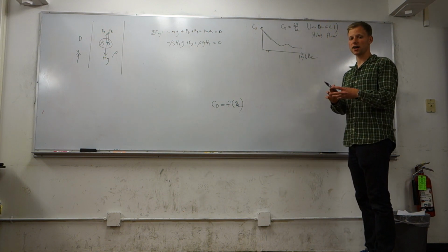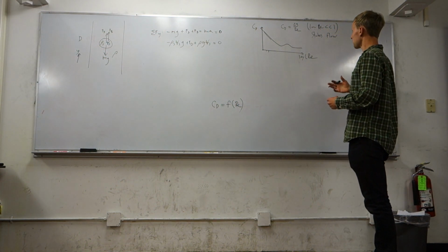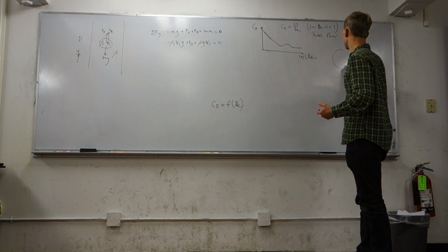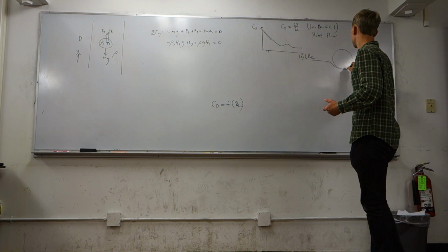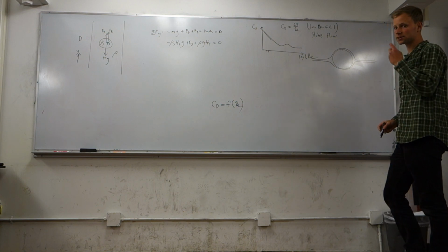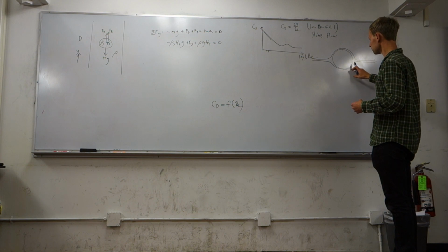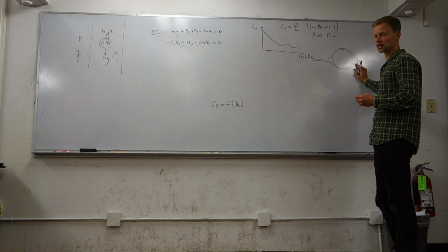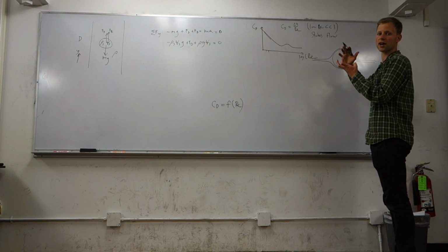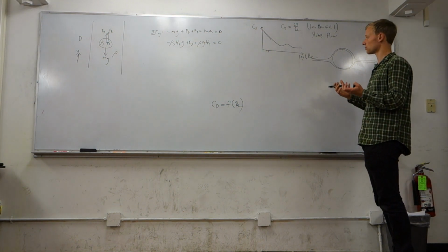We did that thought experiment with the honey traveling around the sphere. We labeled that Stokes flow, and it's the same thing here. Now, given that this is such low Reynolds number, it's very, very laminar. So the flow around this object is very well defined. It just comes in and does not separate around our sphere, and just comes right around it. So what we can actually do is write the Navier-Stokes equations around this sphere, taking into account viscosity, and we can integrate the pressure over the entire area to analytically get what the drag force will be.